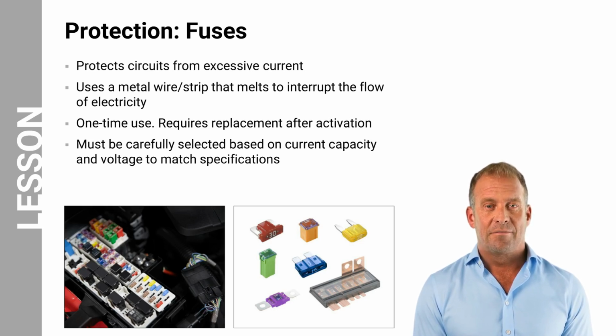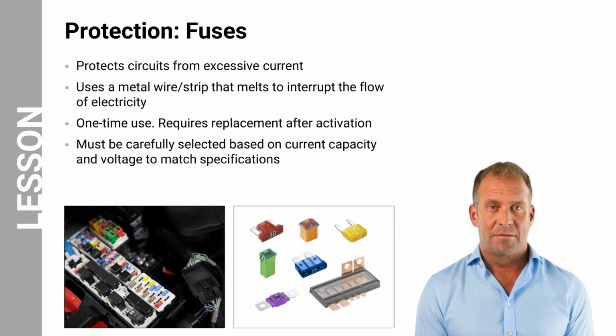Once a fuse is activated due to overcurrent, it becomes a one-time use device and requires replacement to restore circuit functionality. The selection of fuses is a critical aspect of automotive electrical design, as they must be carefully chosen to match the specific current capacity and voltage requirements of the circuit they protect. Too low a rating may result in frequent and unnecessary fuse blowouts, while a rating too high may fail to adequately protect the circuit from overcurrent conditions.